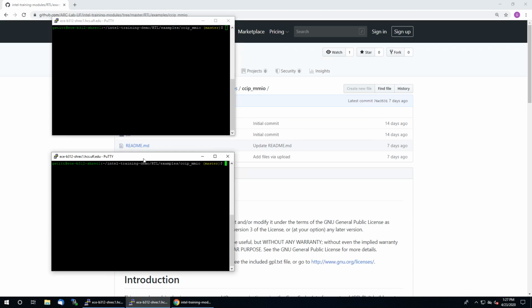So one thing you need to be aware of is that in this video, I'm not going to explain how to install all the tools. So I'm assuming you already have OPAE installed and you already have ModelSim installed. So you will have to use ModelSim SE to use Intel ASE. Now, ideally, you would just do this on the Intel Dev Cloud, but as of right now, there are no ModelSim licenses on the Dev Cloud, so you will have to do this on local resources. But hopefully that will change in the future, in which case you can just do all of this on the Dev Cloud.